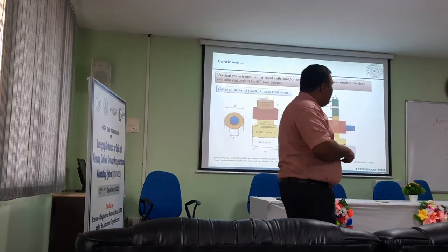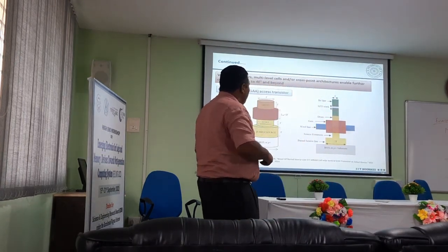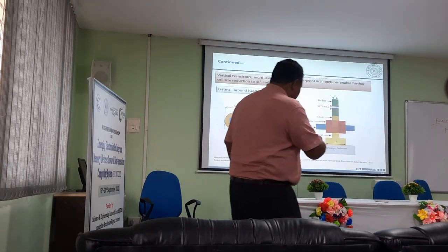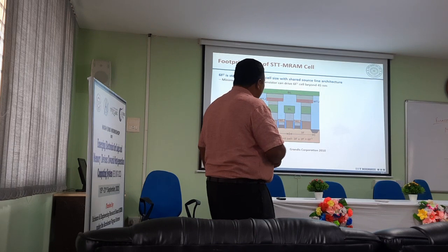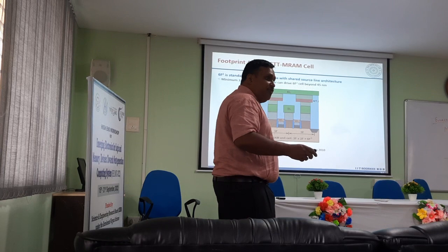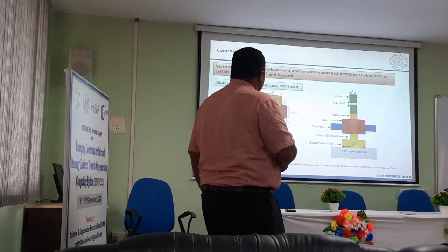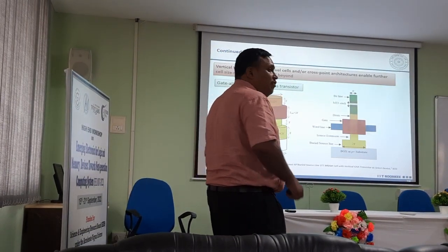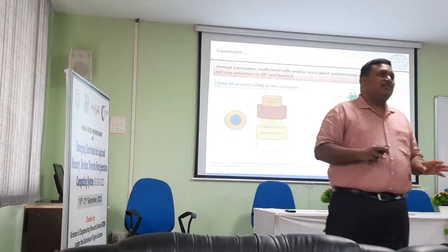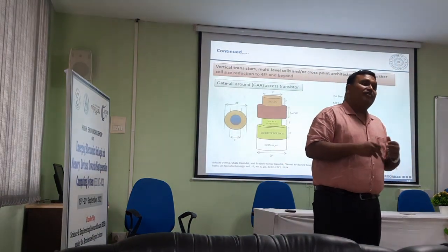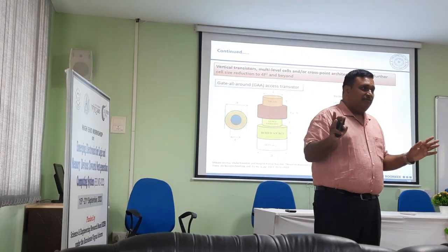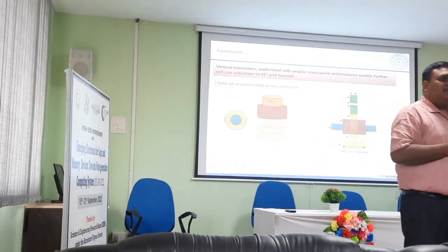And what we realized is that the overall size was reduced by one-third. Previously, for example, Lamb's Corporation came up with a size of 6F², where F is the feature size, and with GAA we could reduce it to 4F². So a 33% reduction in the overall size, with the same performance and same driving current, without any performance issues. This was more specific to the area.